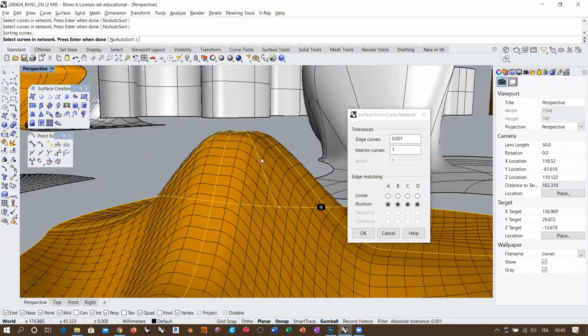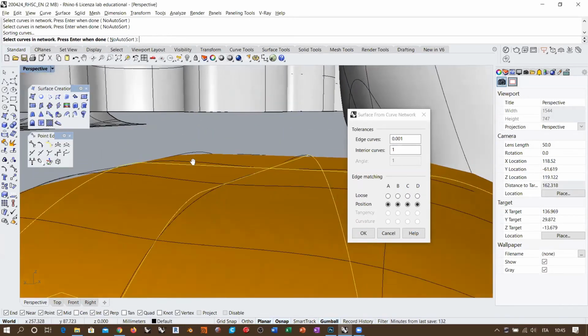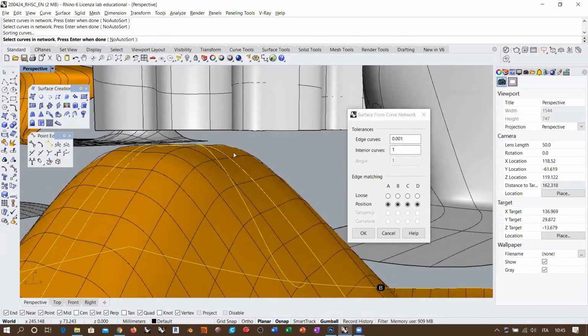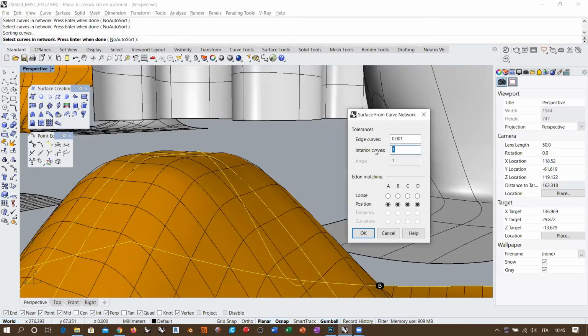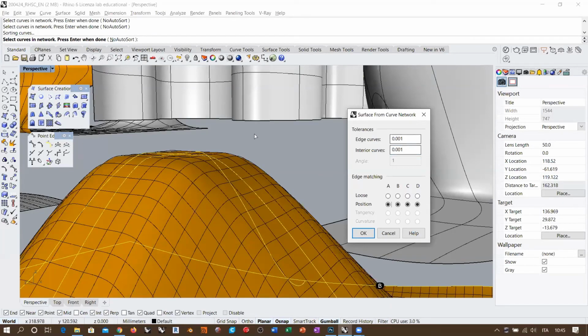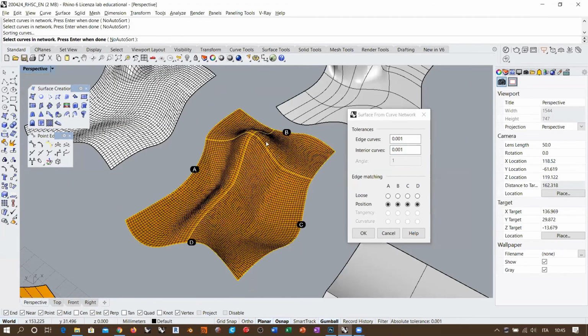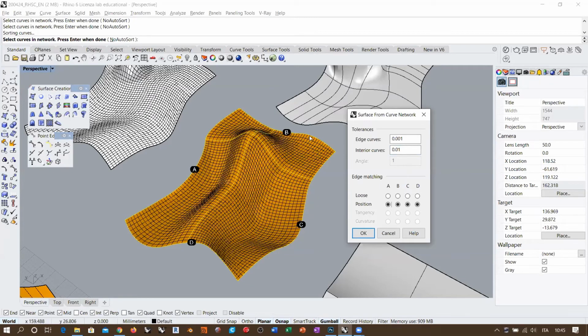In this case, you might notice that the surface starts to move away from the interior edges. But if you want to reach a very precise height, this should also be a very high tolerance value. Anyway, normally this is set to 0.01, because there is enough precision with this tolerance.